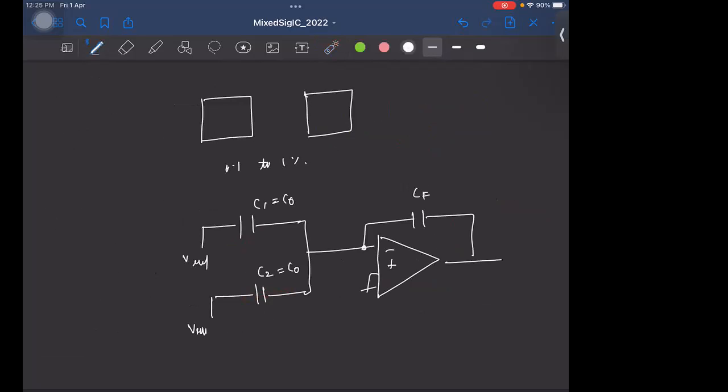And what will be the total charge that is transferred to CF now? No, I mean individually, right? So Vref times C1 plus Vref times C2, right? So the voltage you are realizing is Vref times C1 plus C2. That's the charge that is getting transferred. Now, if you just had one of the branches on, you will have only Vref times C1, right? For example, the code is 1, so that this branch is grounded.